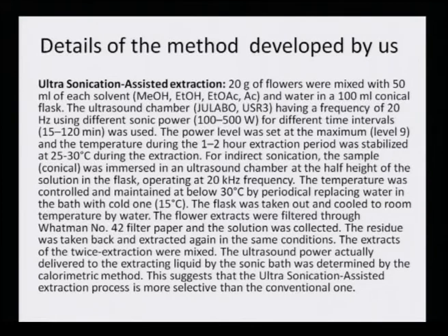The ultrasound chamber, that is the machine that I showed you, was the Julabo machine of model USR3, having a frequency of 20 kilohertz, using different sonic power between 100 to 500 watt for different time intervals, from 15 minutes to even 2 hours.